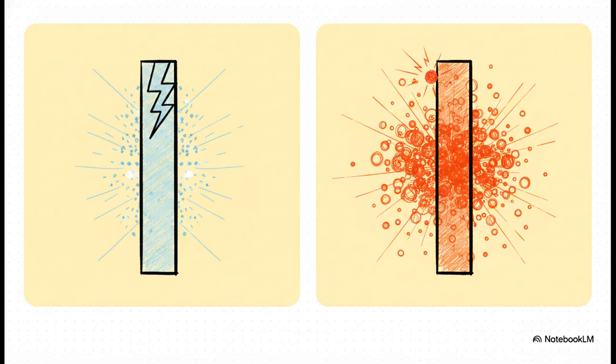The first is Zener breakdown. This happens in heavily doped diodes with really thin junctions. The intense electric field literally rips electrons straight out of their covalent bonds. The second way is avalanche breakdown, which happens in moderately doped diodes with thicker junctions. In this scenario, the high electric field accelerates a few free electrons to such crazy high velocities that they smash right into neighboring atoms, knocking more electrons free in this massive high-speed collision cascade. Literally an avalanche of current.